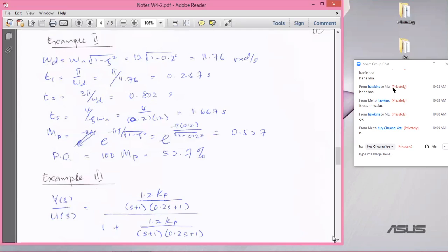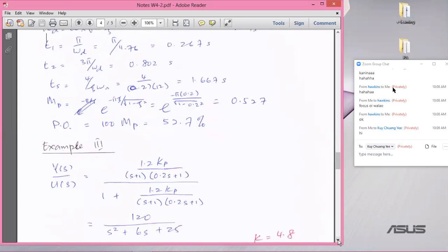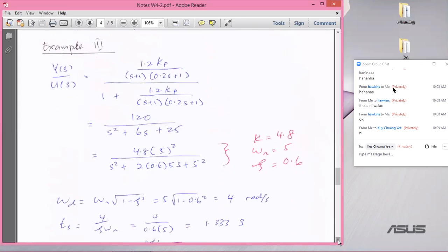All right. Okay, there you go. So the overall transfer function for a feedback, closed loop system is G divided by 1 plus GH. So G is the forward path transfer function. The feedback loop is just 1 over 6. Where is the 1 over 6?